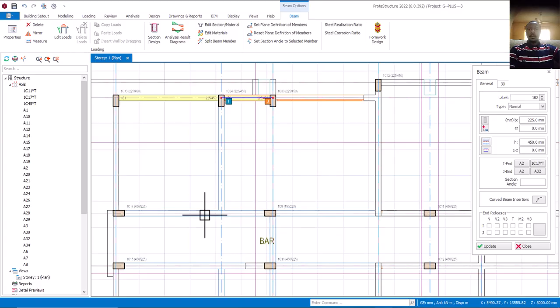Okay, what we will do now, let me escape, or let me undo it. So this one now, click on this, right click and click on offset and bring it down, F2, by minus 225. Is that okay? 225. Enter. Correct. So click on this, delete. Perfect. So you can see your ability to think is very, very important. So come here, offset and take it up by what? Press your F2, that's 225. Enter. That's fine. Click on this, delete.